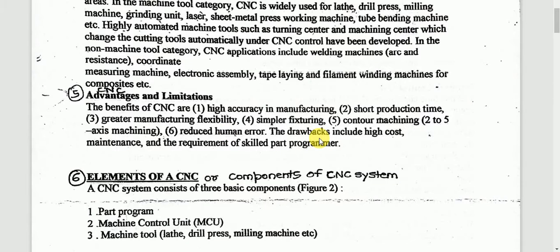Apart from these advantages, there are many other advantages like better control of cutting tool. This is the major advantage of NC machine tool. With NC, we can control the tool very accurately. The cutting tool can be controlled along any type of motion like circular motion or parabolic motion of the tool, etc. Then there is reduced lead time for production. There are fewer chances for human error.